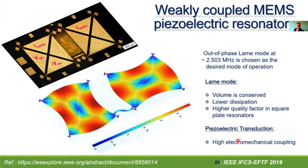Now let me explain about this coupled MEMS resonator design. So this is a free floating coupled MEMS resonator anchored at the four corners. And I have designed this MEMS resonator such that it operates in its Lame mode as opposed to the square extensional mode in the previous work.